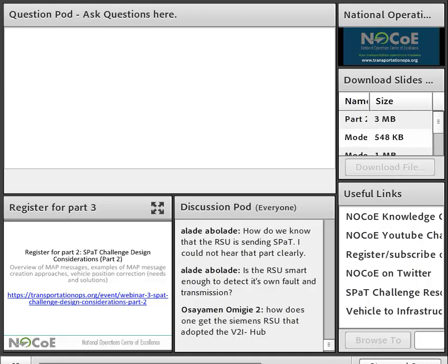Let me ask another question. Is there a handshake between the RSU and the SPaT controller when the information is being sent? And the second question is, how do we know that the RSU is sending SPaT? Is the RSU smart enough to detect its own fault in transmission?